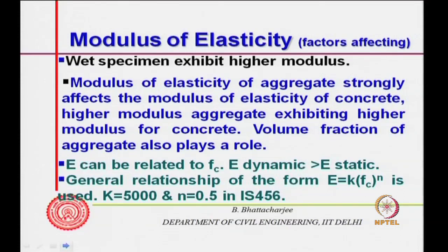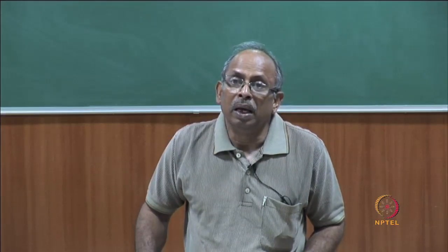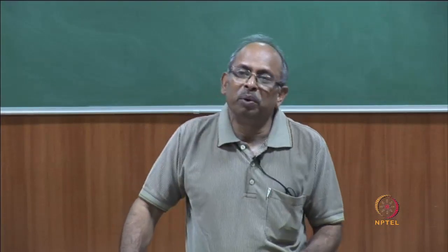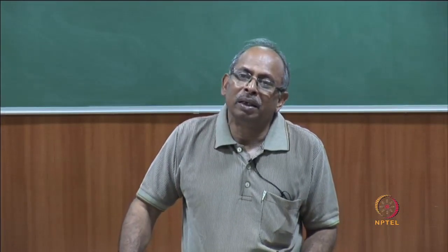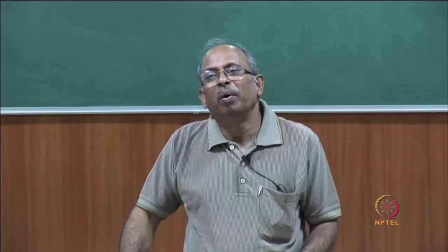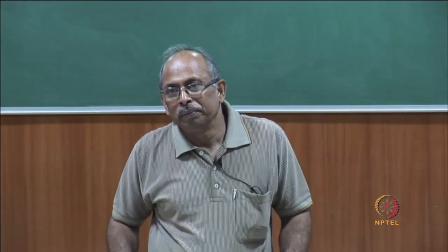Then mostly E can be related to root Fc, well, compressive strength. Now, E can be related to compressive strength. In fact, we have seen that modulus of elasticity governs the strength. Therefore, we can argue that strength would also be related to modulus of elasticity.